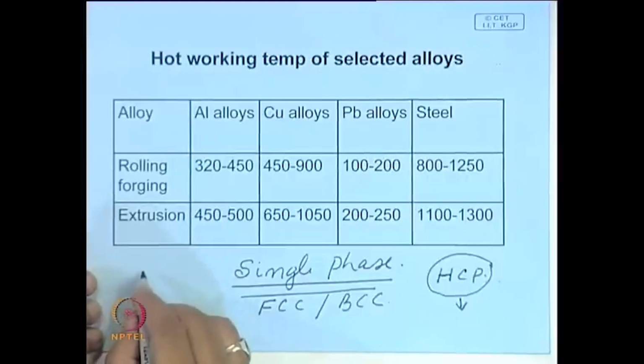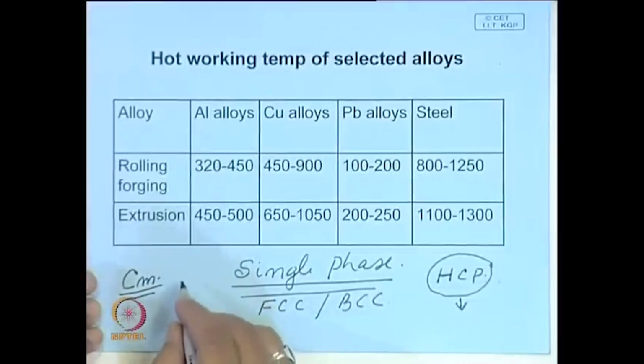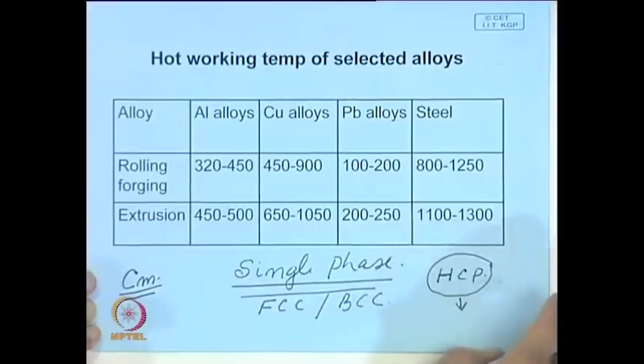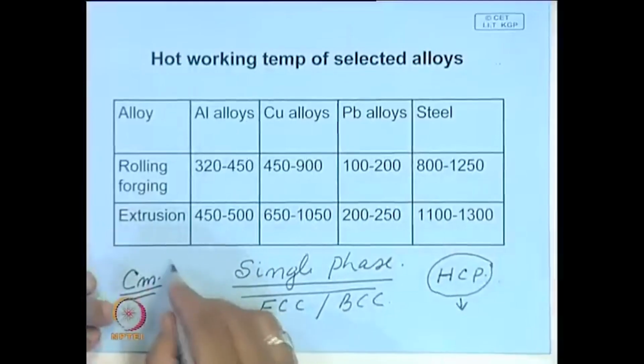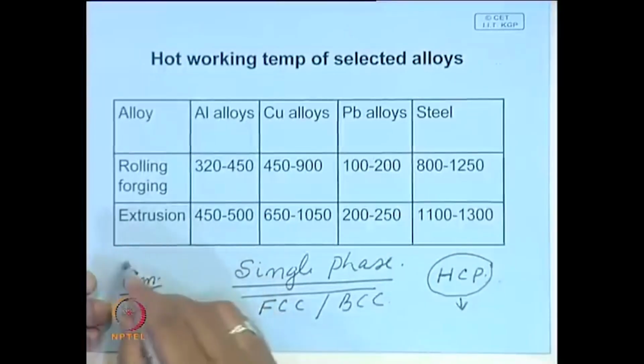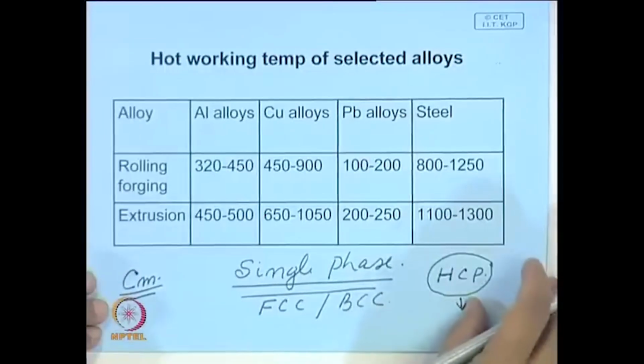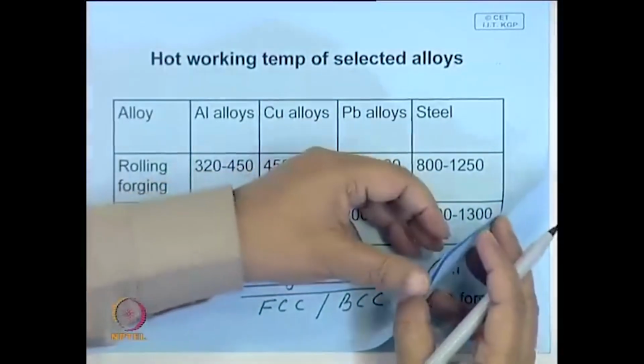Similarly, there are some materials which because of their crystal structure are inherently very hard. Even if you have carbides like cementite or some of these intermetallics, they are very hard, they are difficult to deform. They can fragment, but the point is it depends on whether they are present in bulk quantity, then it will be even more difficult to deform. So, the microstructure is quite important to know whether the material can be processed by deformation processing.